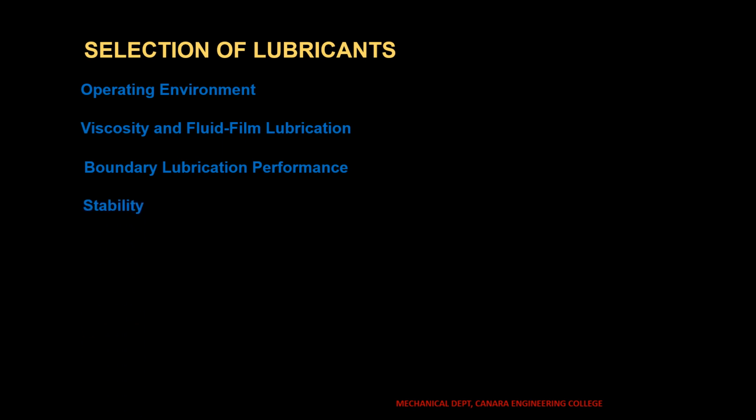Stability. If the upper operating temperature limit for a liquid lubricant is not defined by the viscosity temperature properties, it is generally defined by stability of the lubricant. A lubricant must be stable in the environment in which it is being used so that it provides adequate lubrication for the finite lifetime.